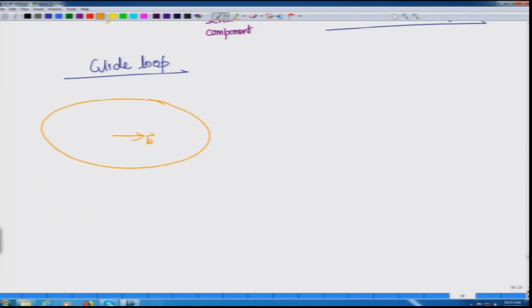So, over here, like I said, this is perpendicular. So, you can imagine there is an edge dislocation. On the other side also there is edge dislocation of opposite character, and since you are over here, there will be some screw dislocation, which will be, let us say, right handed side, and if you go to this side, there is a pure screw dislocation at one point, and it will be left handed side. So, the edge character is continuously changing, and the drawing of how the atoms are arranged is something we have already seen.